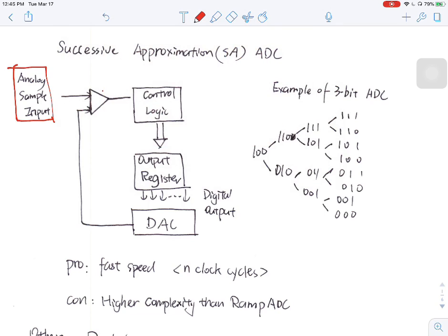If we have an analog signal that starts from 0 volt all the way to 3 volt, what we learned in DAC is we can map the range between 0 volt and 3 volt into a sequence of digital numbers all the way from 000 to 111, right? And each binary code represents a value of the analog signal. Yeah, we did that last week.